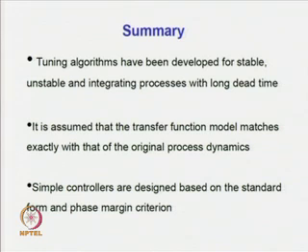Now, simple controllers are designed based on the standard form and phase margin criterion. So, GC and GC1 are designed based on standard forms, and GC2 is designed based on phase margin criterion. It can be optimum phase margin criterion, it can be ordinary phase margin criterion.